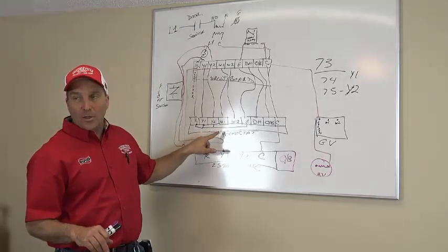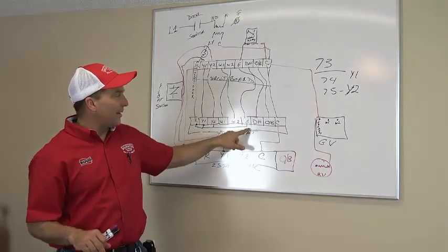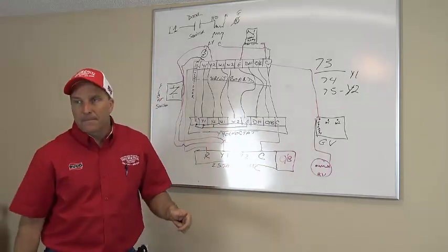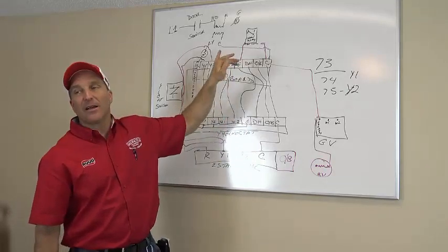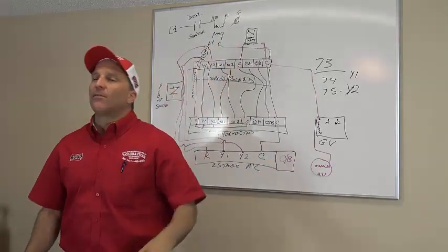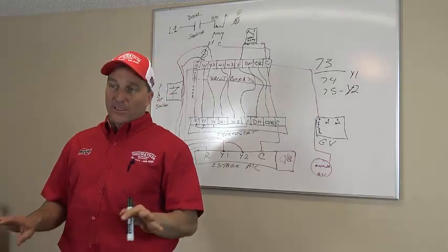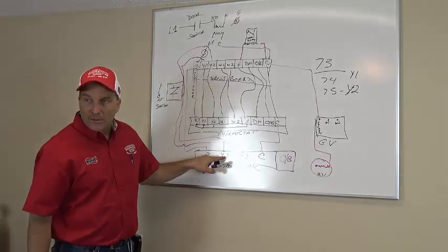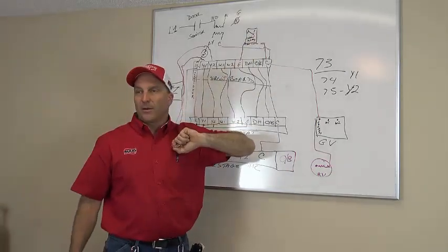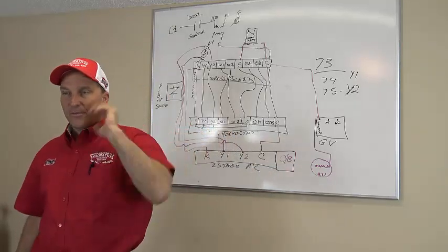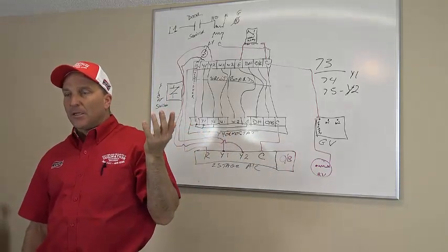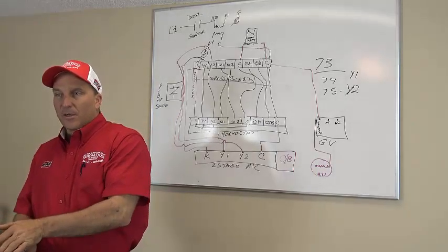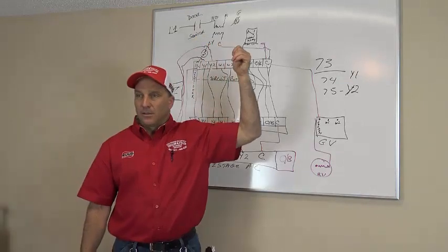Because I energized cooling, it automatically energizes G. So anytime Y touches, G's touching too, right? So G gets energized, which energizes a fan relay by itself, which is low fan on some of these old systems. So now I've got Y1 running on my compressor and low fan running on my air conditioning system, because the fan relay is energized. So now first stage cooling is the compressor running in first stage, 70% capacity, with the blower motor running in low speed.